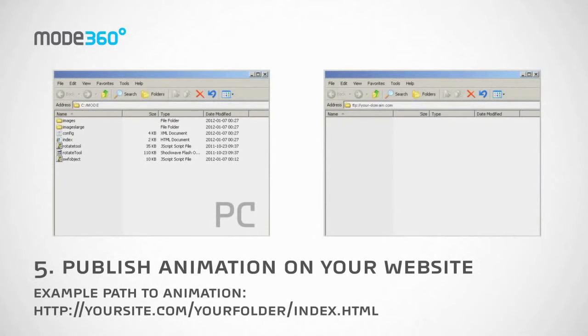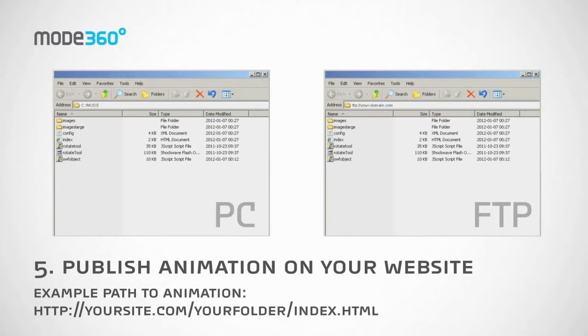When publishing animation online, establish an FTP connection by any FTP program or Windows Explorer and copy all files from the 3DRT Flexi Output folder to a newly created folder on the server. After all files are copied, type your FTP folder path in your browser and share it with your customers.